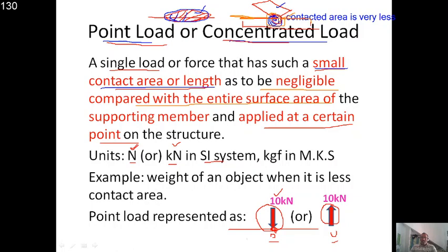When compared to the span, it is very negligible. So it is acting at a very small contact area. A load acting on a span at a very small contact area or length is also known as a point load or concentrated load.